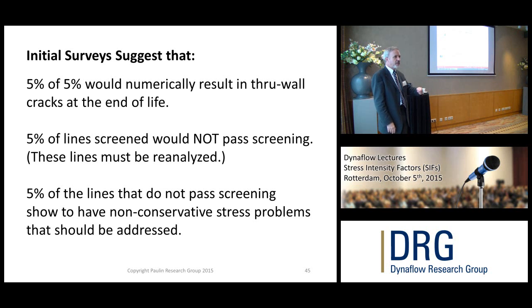And it'll be some sort of phased array more than likely, because that's the most sensitive volumetric inspection that we can have that requires the least amount of technology. In 10 years it'll probably be different, but that is the way it is today. So we're writing specs for phased array inspection today. And the interesting thing is you will find damaged material with phased array that you can't see with fluorescent particle inspection, fluorescent penetrant, or even regular penetrant inspection. Penetrant inspections don't find a flaw where phased array sees big red. So you can validate that this is a place that's been overstressed.